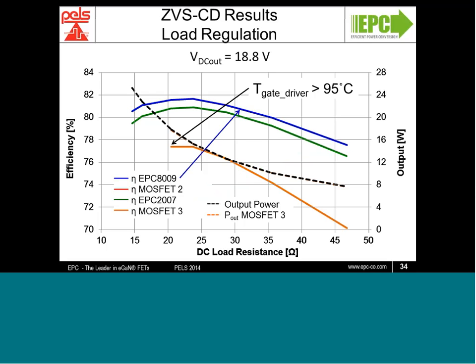And lastly, we have the MOSFET here, showing that the performance is still lower than the GaN FET, but on the high load resistance end, it has a lower on voltage for the diode conduction portion, and therefore that slope comes down at a lower rate. These are issues that can be easily fixed for the gate circuit for the GaN FET.